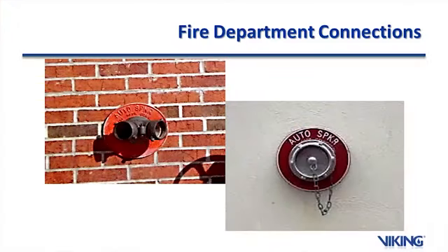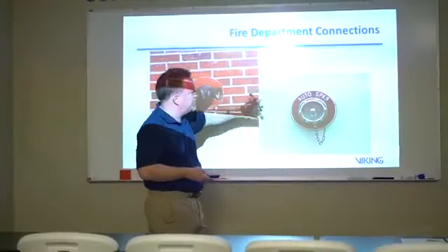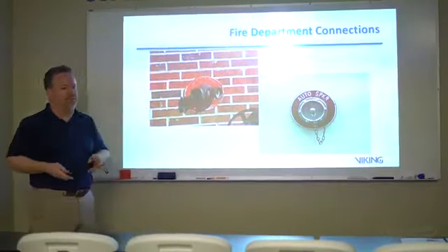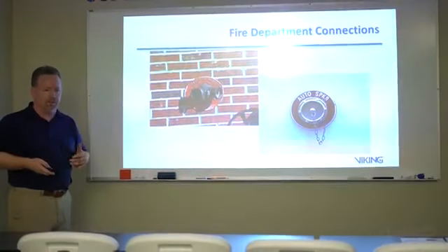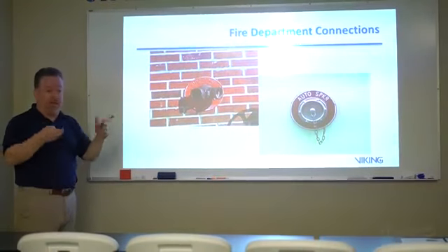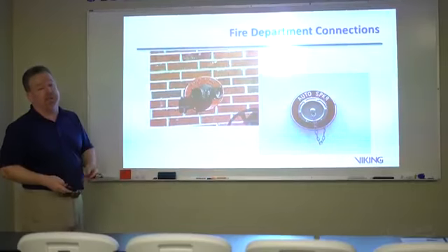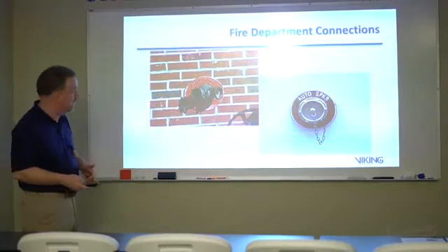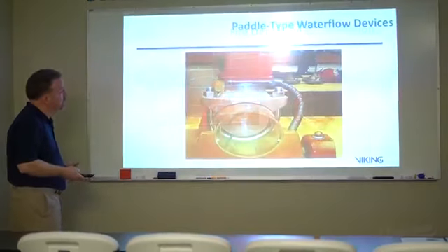Fire department connections, 2 different types. Providing water, either a Siamese connection or 6-inch or 5-inch, a quick connect onto those particular items. Again, you're basically doing that based on whatever the local fire department uses. You're going to be installing that type of a connection.